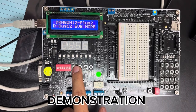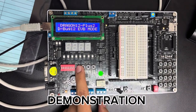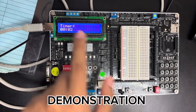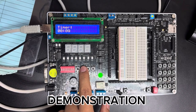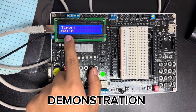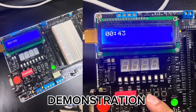So how this device works is the program will enter a wait state until the start button is pressed. Once started, the timer increments every second, displaying the elapsed time in minute and second format. If the stop button is pressed, the program pauses and plays a buzzer tone before resetting to the original wait state.